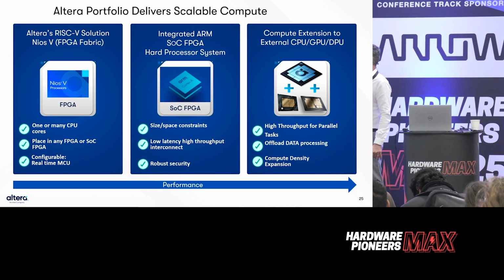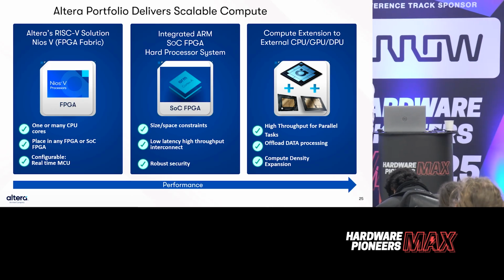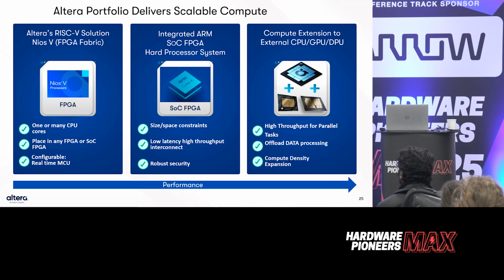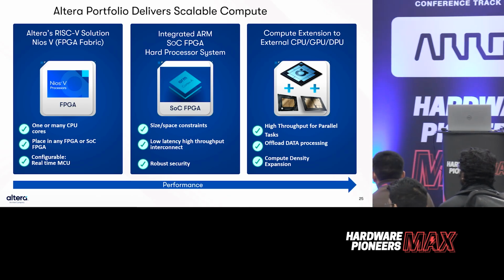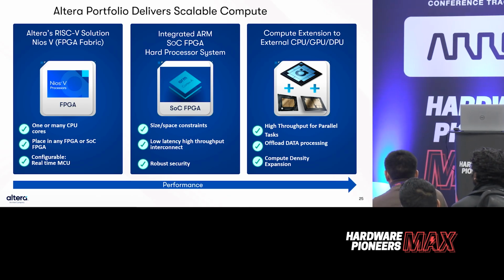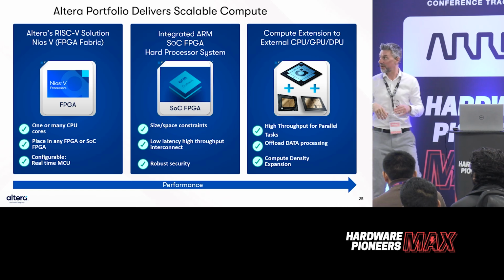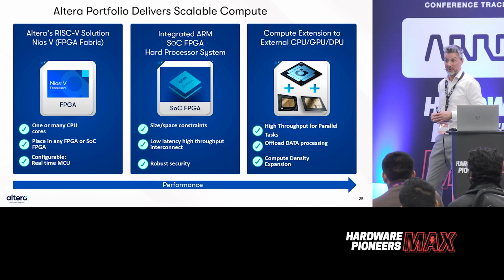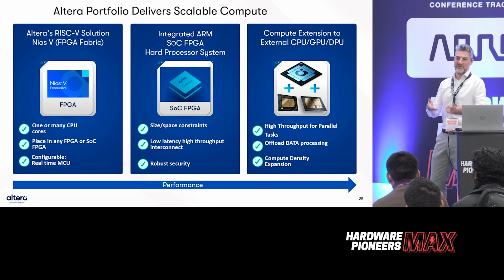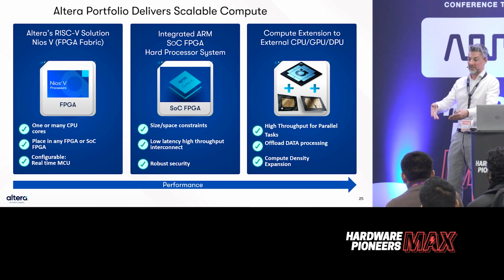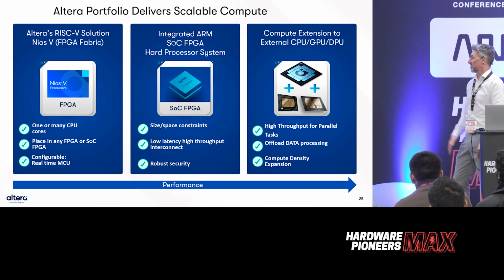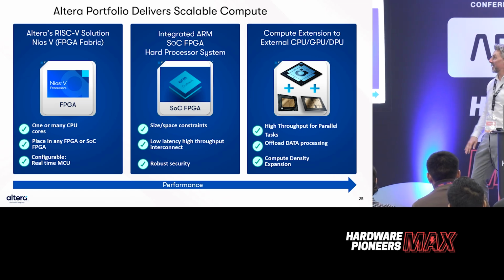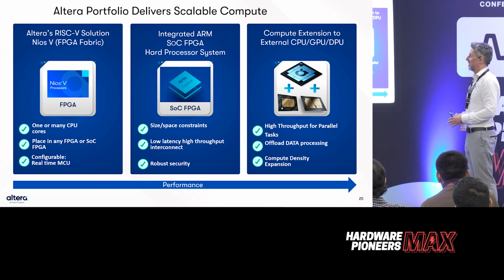We started off with A9 processors. We've got A53s, A55s, and A76s in the latest family. So you'll see quite a lot of ARM processors, and all the guys will have ARM cores inside their FPGAs, because a lot of people use them for often just running Linux, for example. You've got a Linux application class processor running Linux there on the FPGA. You can use it for lots of stuff, even if it's just board management or little bits of twiddling around the edges. It's quite an easy way of getting a processor up and running.